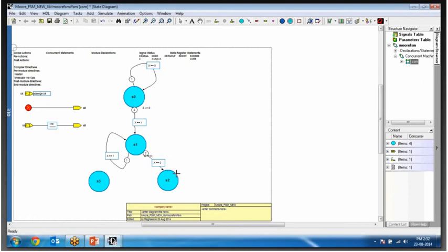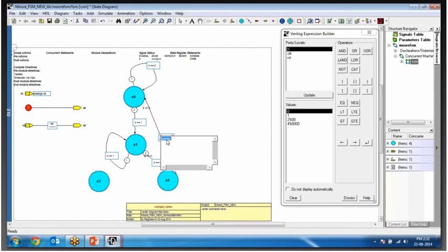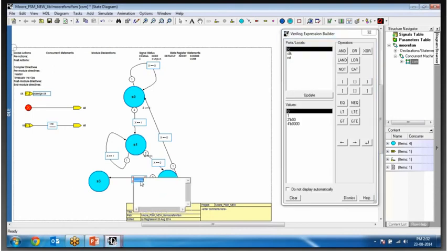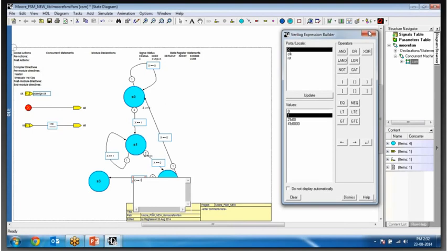So for that, another transition. I'll quickly complete this. If we find 0 again, go back to state 0. Again, after 1, we are finding 0. After 0, again if you are finding 0, go to state 0. If we are finding 1 again, go from state 2 to state 3. For that, a transition. So x equals 1 this time. So this has been assigned.